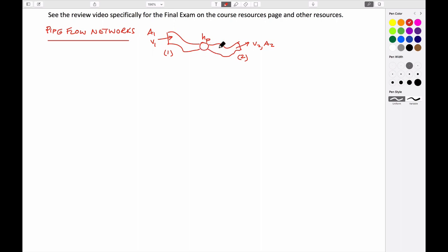That we can have energy added into the system by a pump, and also pump or head losses within the system. And our Bernoulli equation is written in a standard way. If you write it in terms that include length, then it's the elevation, pressure, and velocity heads with a component that represents the pump within the system, and that has to be equal to the downstream components of elevation, pressure, and velocity head, plus the sum of losses that occur from both minor and major components. Minor being bends, etc., major being the slow but ultimately large changes in head that result from pipe flow losses.